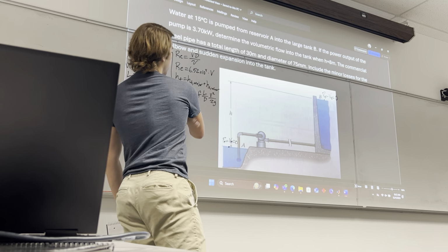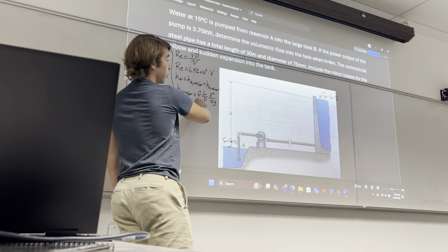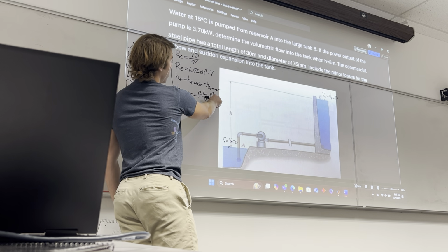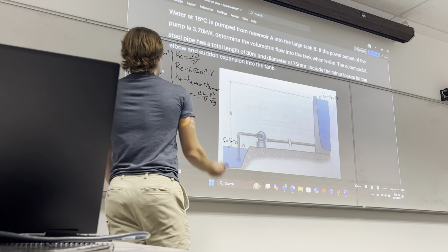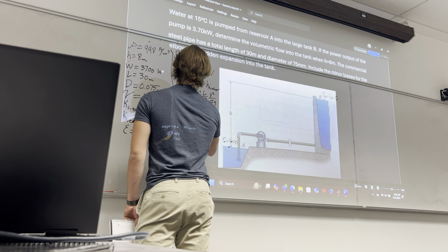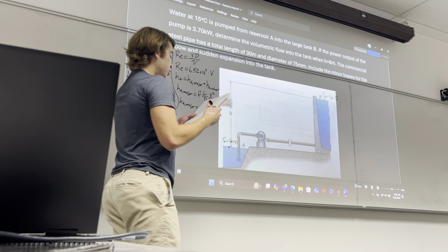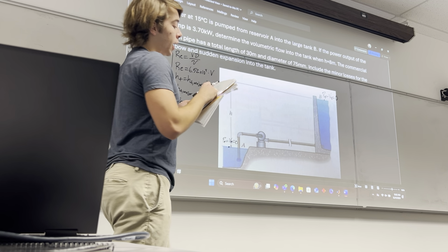So first, let's just plug in what we know. In this case, this will be solved in terms of the friction factor we don't know and the velocity squared we don't know. But everything else we know, so let's just plug it in. So HF major equals F V squared times 20.3874.